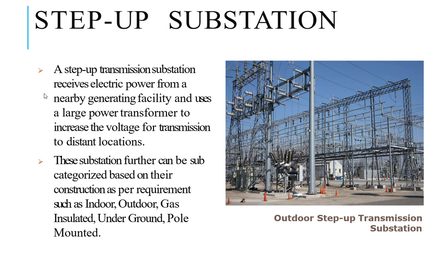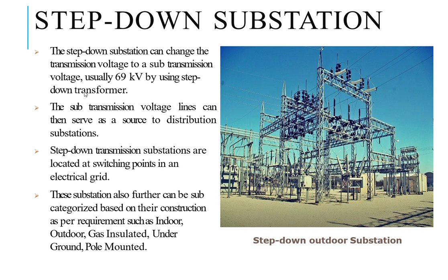Yes, step-up substation is the type of substation which receives electrical power from a nearby generation facility and uses large power transformers to increase the voltage for transmission to distance location. These transformers have been rated in higher kVA. Substation can be further categorized based on their construction per requirement, such as indoor, outdoor, gas insulated, or underground pole mounted.